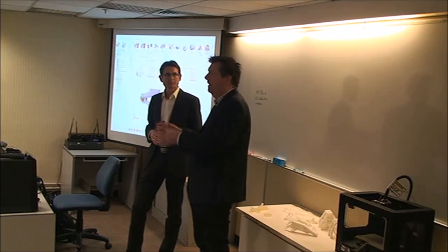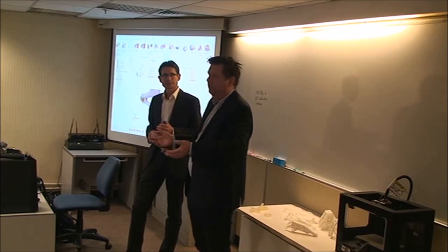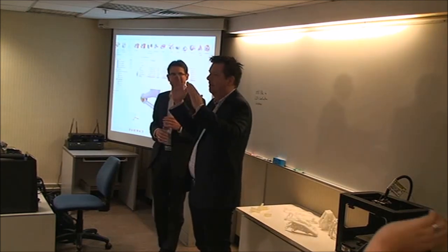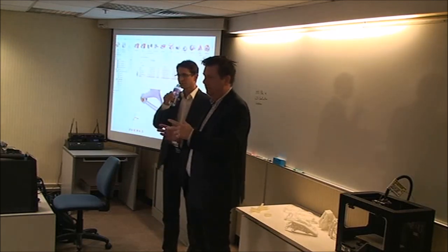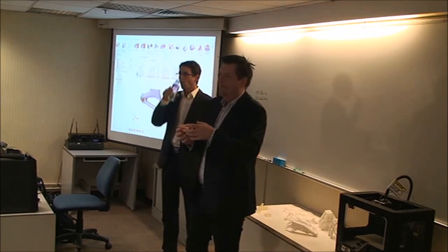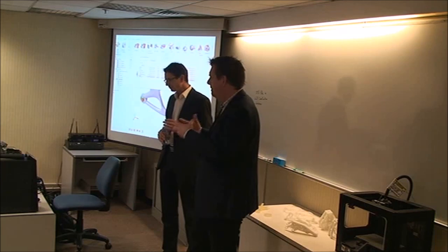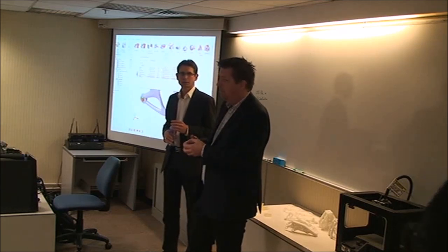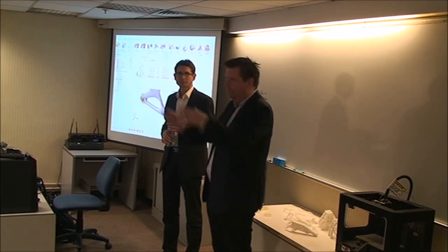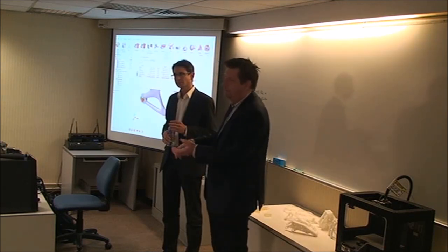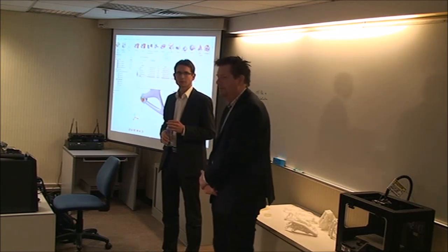You can have multi-parts as multi-materials, but if you're building a bridge and you want the optimum member layout, it's pretty much going to be the same layout whether it's concrete, reinforced concrete or steel. It's just how much concrete and reinforcing you put in versus how many steel columns. So Inspire still tells you where to put the material, no matter what the material. It might be more, but it will still be aligned the same, or you might need extra supporting for buckling. Your main locations don't seem to change very much.